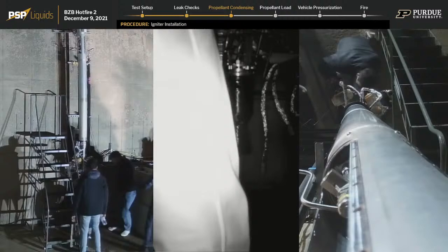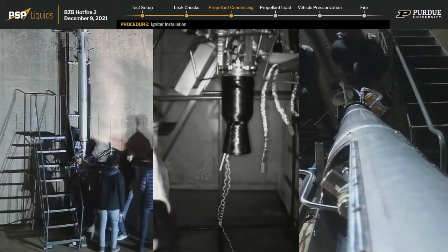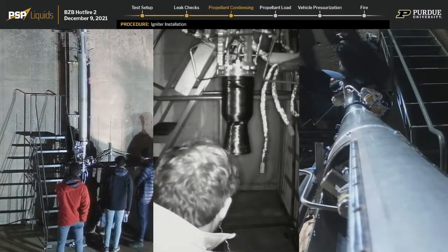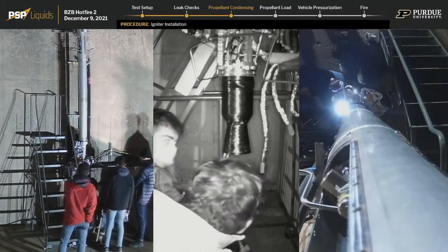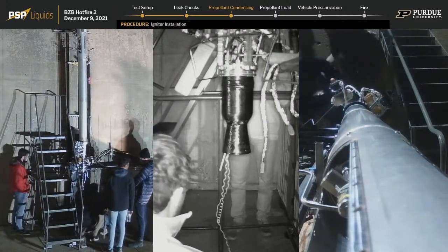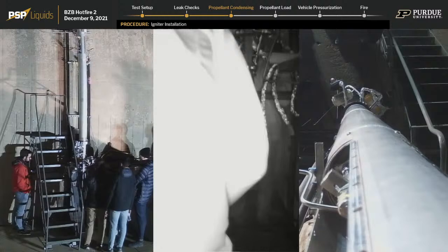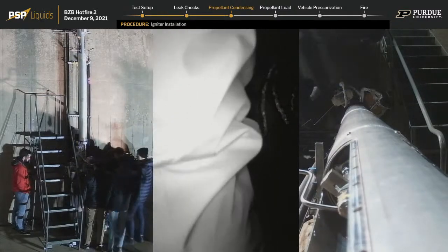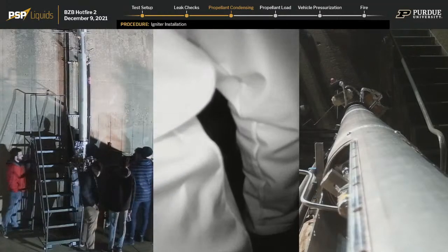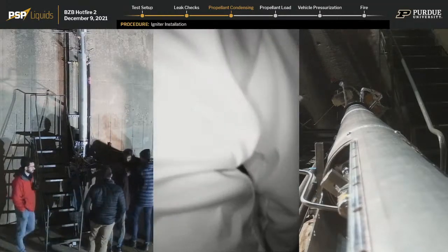Sometimes, we don't often install igniters, so it seems we've deviated slightly. Okay, I'm going to get back and verify some things at the courtyard. Can we verify that the igniter leads are disconnected from the igniter Wago block? The leads are right now disconnected from the Wago block. Over. Can we verify the continuity across the igniter leads with a multimeter?